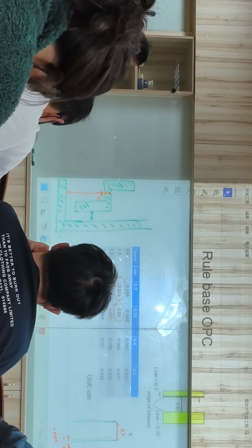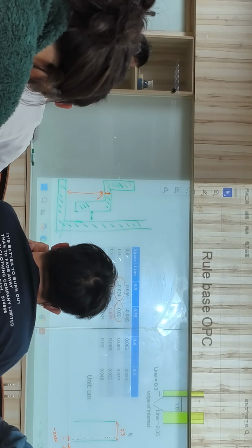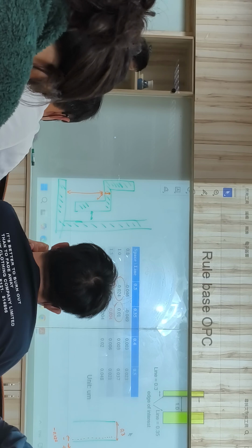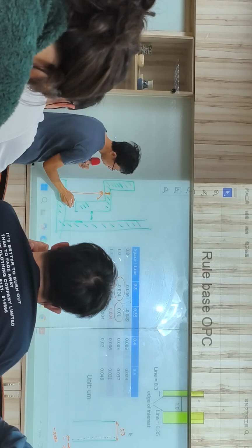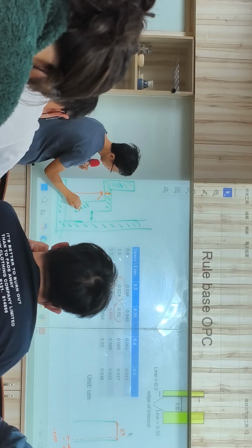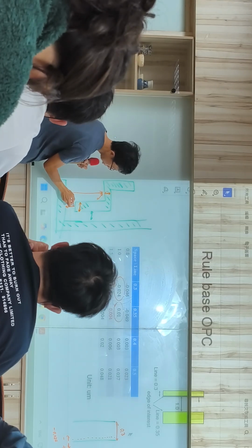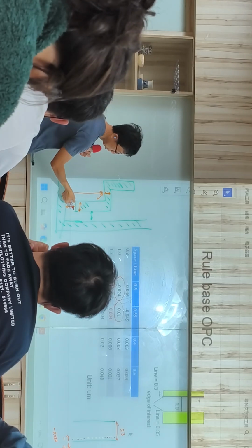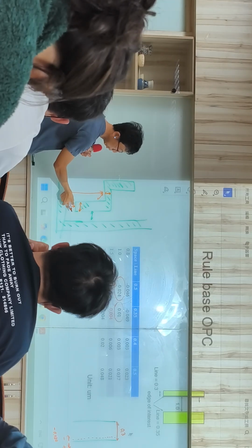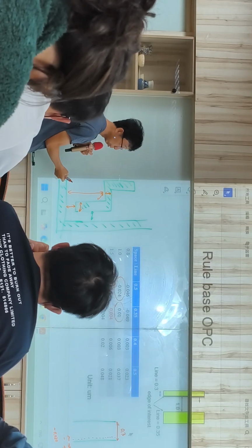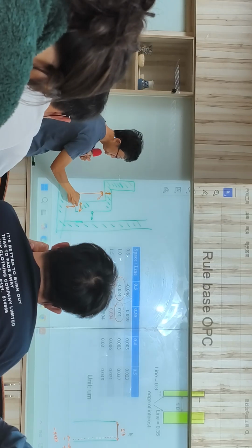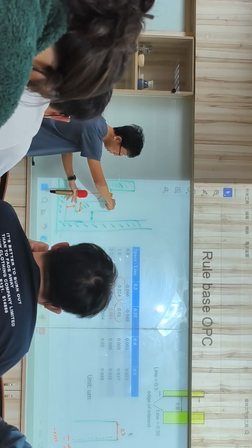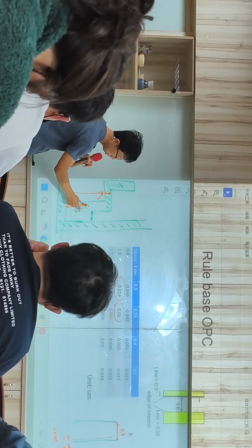Okay? So for two-dimensional patterns, the rule-based OPC will become weak, right? Like here, for example, you know the CD here, but how do you judge this one, right? Your line is here. Your space is this one. It's not in the same direction, right? How do you judge or making a rule like this? Do you use a line this way, or you use a line this way?